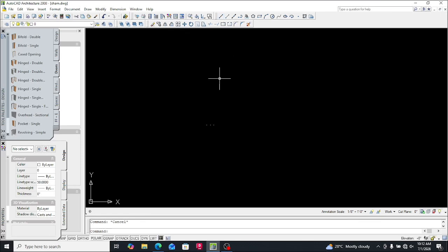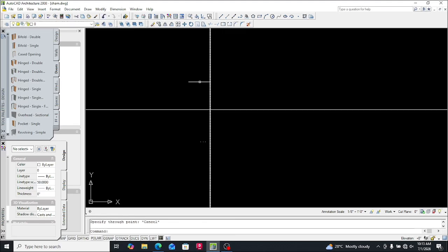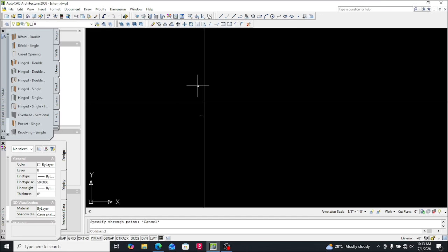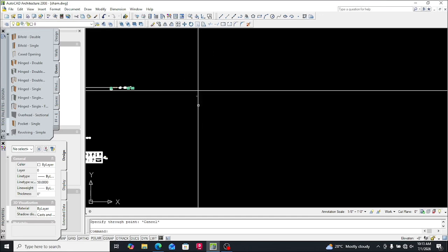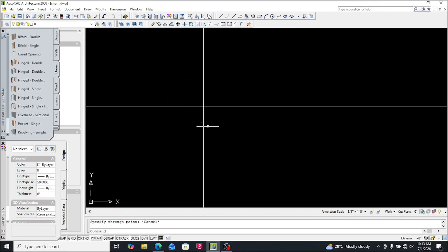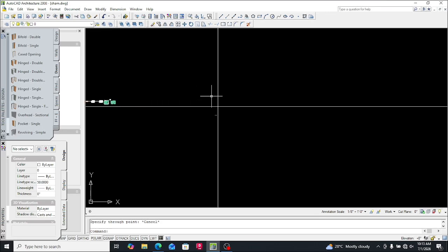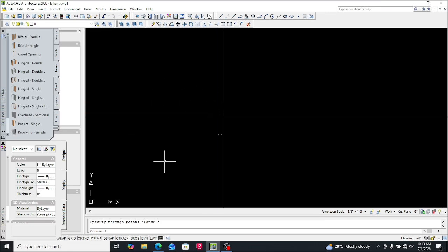Then I'm going to use extensional line for it, and after that I insert the walls. So the extensional line is XL. Alright, now the rooms, the inner dimensions for each room, I'm going to do it 12 feet, 12 feet, 12 feet, 12 feet. So I'm going to make the bedroom to be at this side.